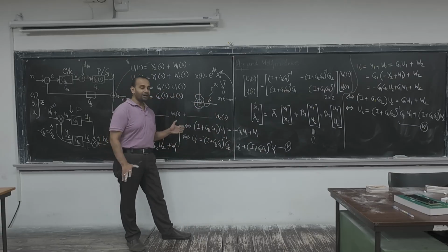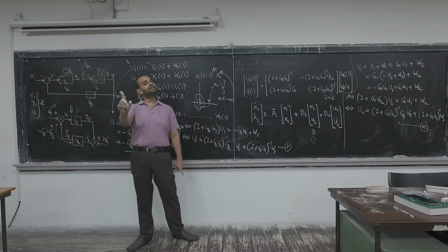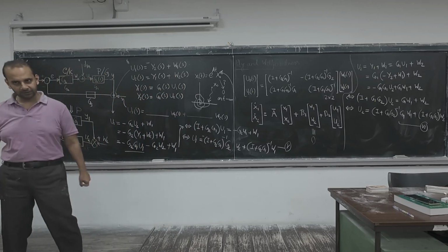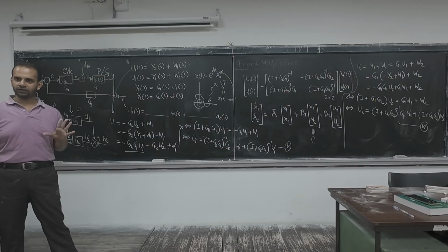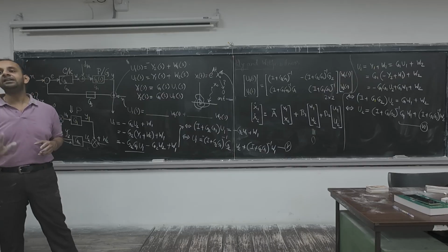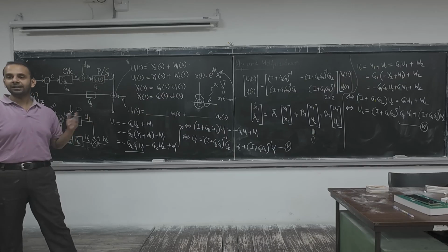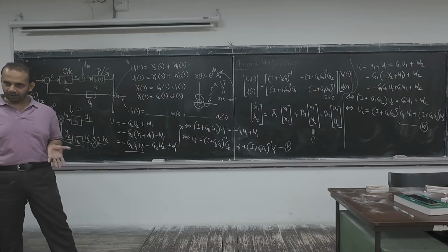But now, what kind of gain is being contributed by these elements? That is the matter of concern, right? Now we know that both G1 and G2 are real rational proper transfer functions. Up to that much we can guarantee. But if you say that both of them are asymptotically stable, then that is a highly conservative assumption, because in that case we cannot deal with unstable systems, right?